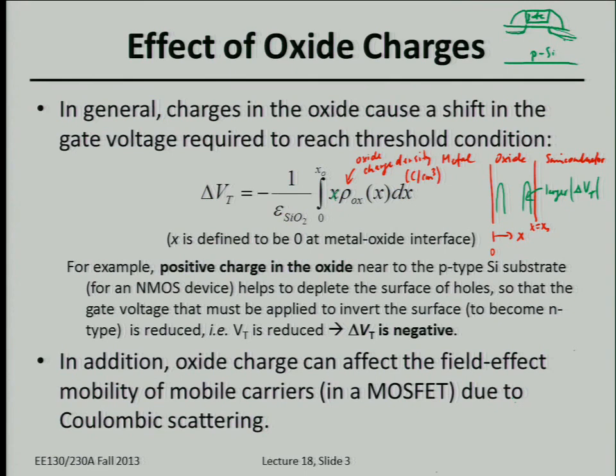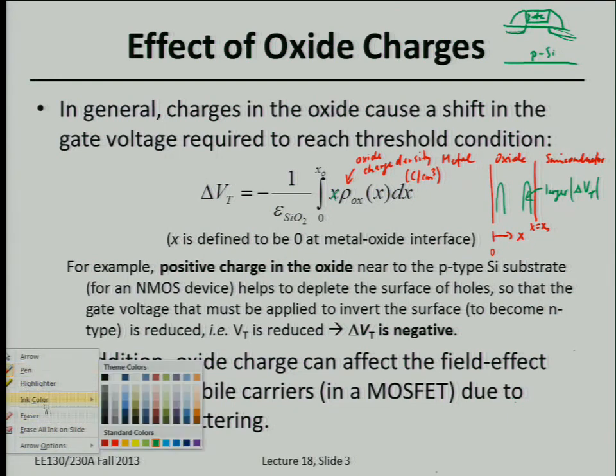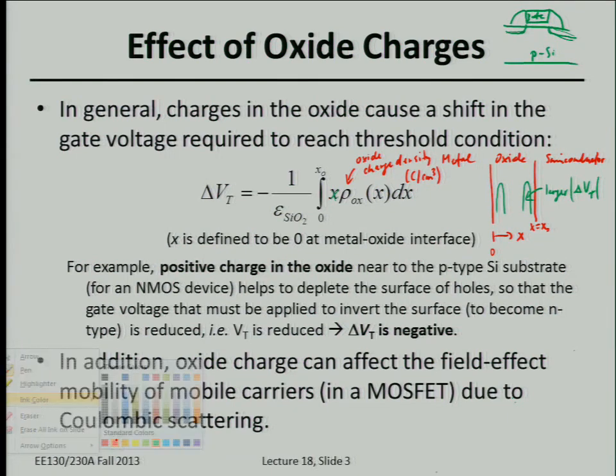It's very difficult to make these junctions less than 6 nanometers in depth. So what people have done in the past, and this is just research, is purposely implant some ions. Turns out cesium is not bad for this. Cesium is a larger atom than potassium and sodium, so it doesn't really move around too much in the oxide, but it has a positive charge.